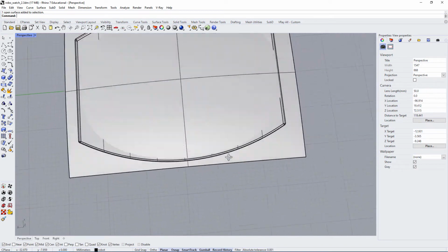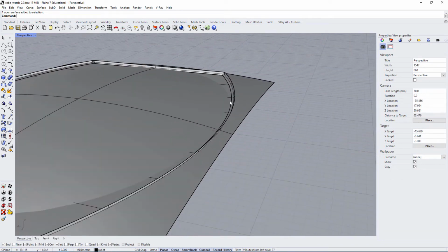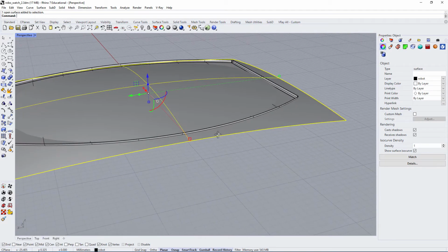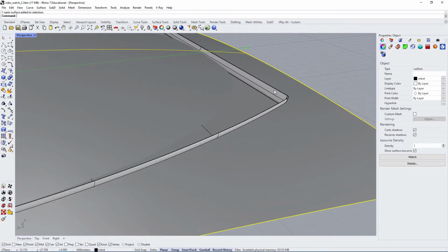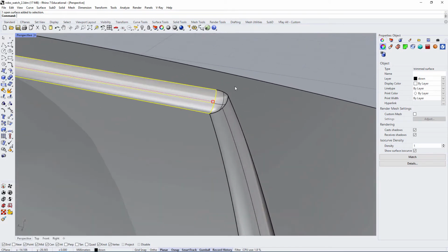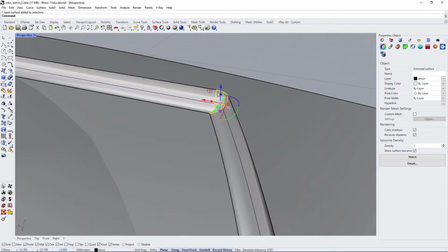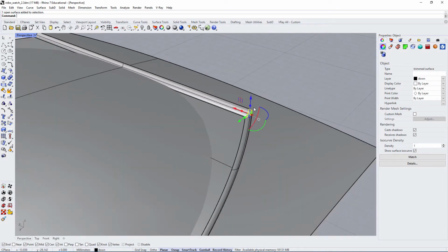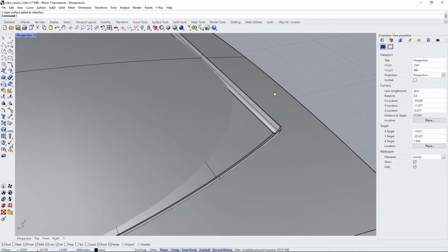transitional. And so the first thing we want to do is cut this surface in a way that will work well with this upper edge. You can see this upper edge here has 4 sides, but also 4 corners. And these are ball corners, but they're also three-sided. We usually want to avoid three-sided surfaces, especially for complex transitional surfaces.